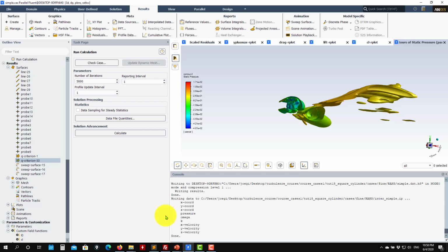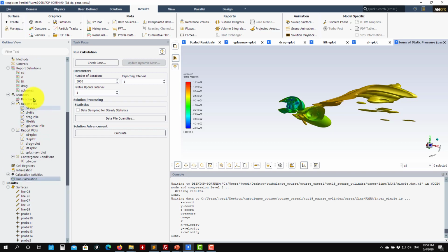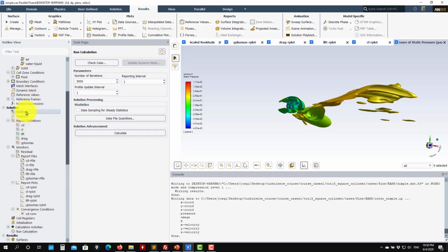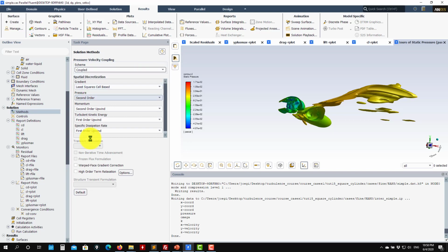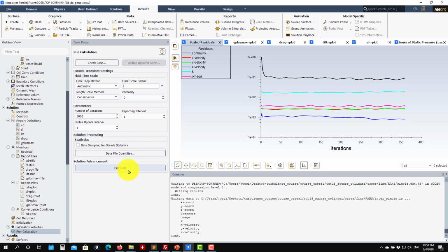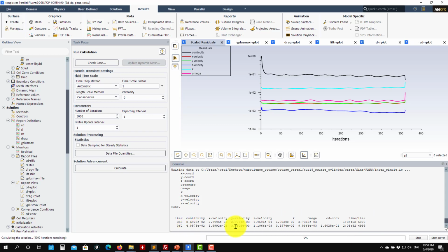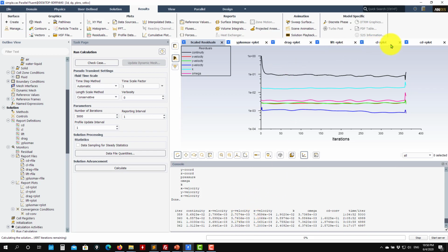Before stopping here, let's do something also. Let's get the interpolation file for the coupled solver and the fine mesh. So you go into methods, change here to coupled, and let's launch this one. And again, it should be something fast. Okay, but interesting, look at that, the cost per iteration is much higher. You'll realize that it's probably like 5 or 6 times higher than the SIMPLE. Okay, so let's wait for this solution, and then we move to the next part.